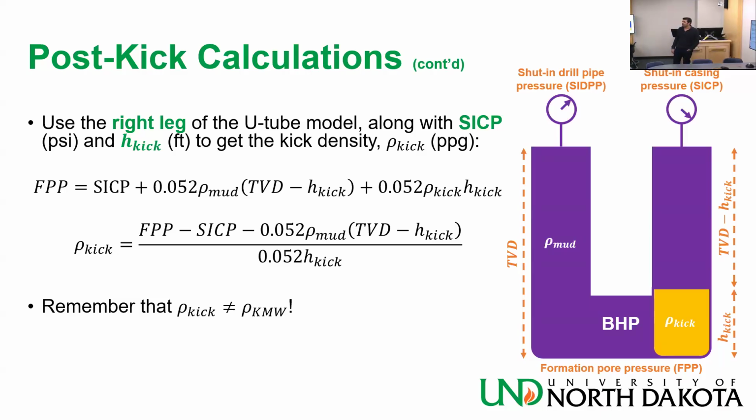Actually, you can have the density of the fluid in a formation related to pressure and temperature through an equation of state. This is what you learn in thermodynamics: the Van der Waals equation of state, the Peng-Robinson equation of state, and several more. There is one called SRK, and some others that are very well used in the petroleum industry for oil and gas fluids.